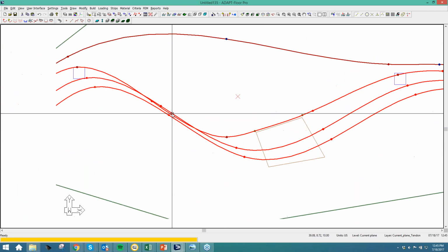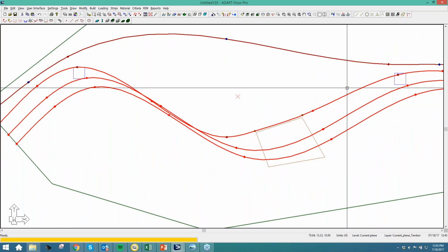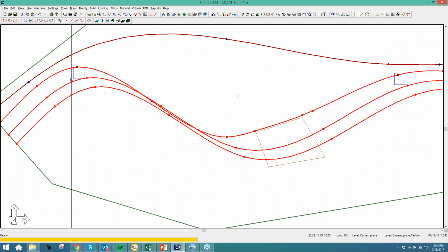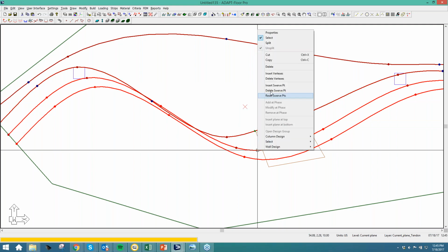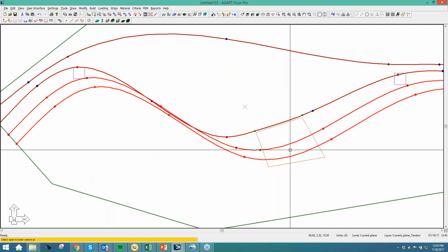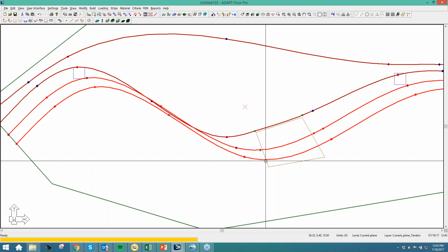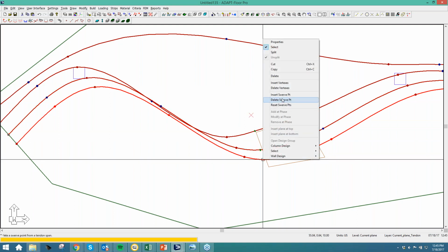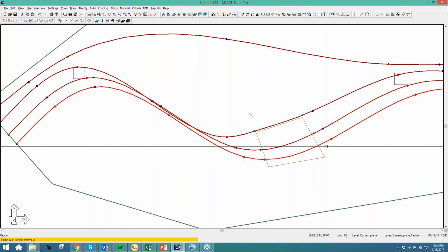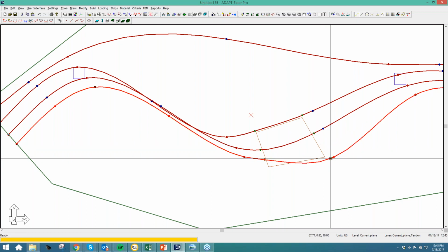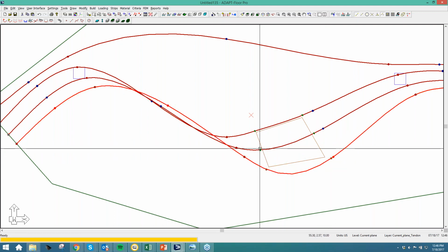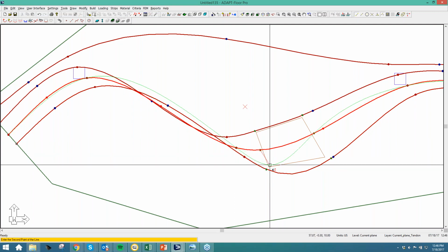And what's beautiful about this is that I have a tendon curvature already, right? There's a profile vertically of this tendon, and by me assigning these swerve points, I am not changing that profile at all. I'm just simply moving this in plan. So the horizontal curvature will respect the vertical profile that's already been established.